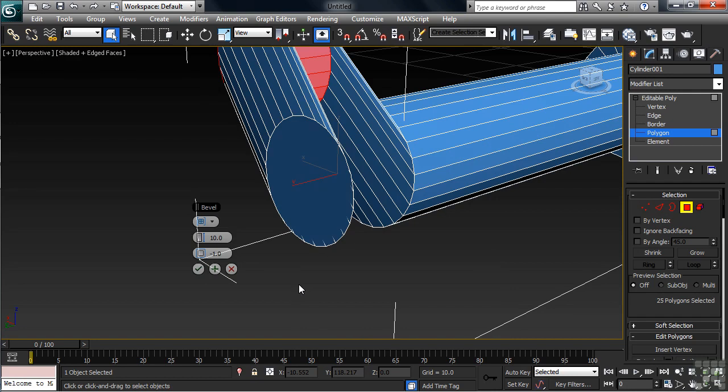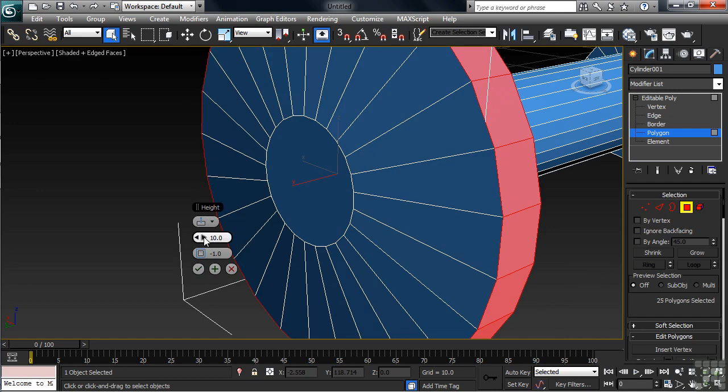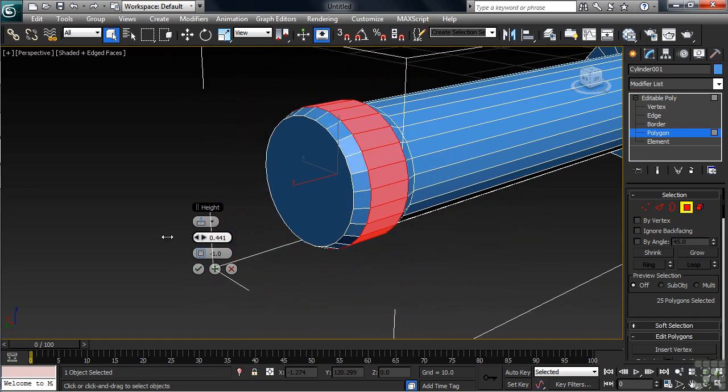In the caddy on the second level, change by local normal. The third level will take down quite a ways. Then, why don't we force in the value by double-clicking and typing 0.3. For the outline, let's take that to negative 0.5. Okay, we're going to want to agree to what we've done, but we want to continue to add another bevel. This time around, on the bottom row, instead of clicking on the green check mark, we'll go to the middle, clicking on the green plus sign.